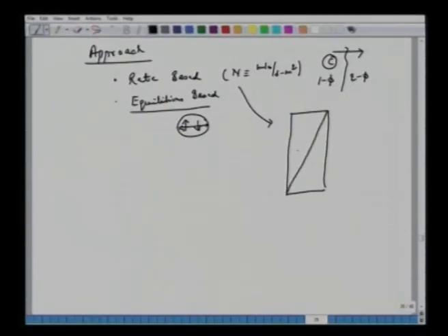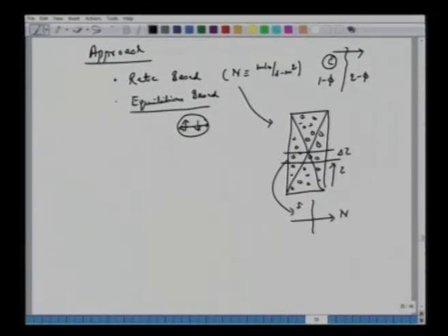Again, talking of some example, for rate based, the most common example would be this packed bed. So here we have packed bed, packing. We have some solids which provide very large interfacial area between two phases. We'll come back to these aspects in detail later in the class. Right now we are saying that if you look at any distance, let's say Z, we choose del Z. Here there is a finite rate N at which sulfur dioxide is getting transferred from air to water phase.